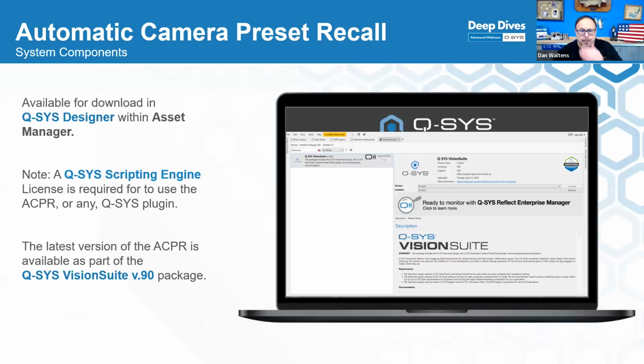ACPR is a plugin. It's found in the Q-SYS Designer Asset Manager. If you're familiar with the software, you can click on the little gear there, or you can go to Tools down to Asset Manager, and it's available. New versions as they become available can be downloaded there. You can open Asset Manager, search for camera, and click Install. Be sure to read the recent release notes.